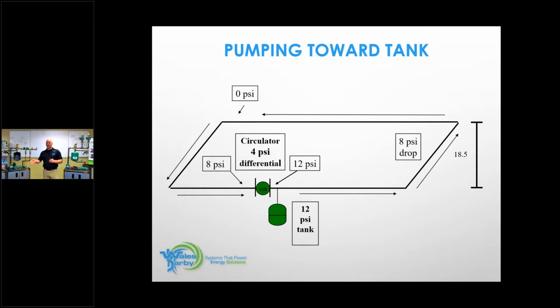So what is the solution? I can't give you a problem without giving you some type of a solution. If you have the ability to elevate the pressure within the system a little bit to try to maintain some pressure up at that highest point, that may work. If that does not work, adding an air can up there in that top corner is also not the answer.